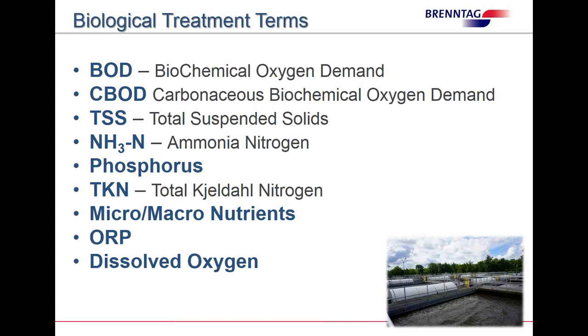Now BOD, we used to run what was called a TBOD, a total BOD. And now they run what's called a CBOD, which is carbonaceous BOD. Carbonaceous is the food that the bugs eat. Sugar, spice, everything nice, so to speak. So anyway, TBOD measured everything that caused the biology to demand oxygen. CBOD just gets the carbon portion of it.